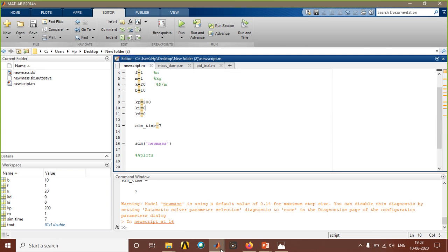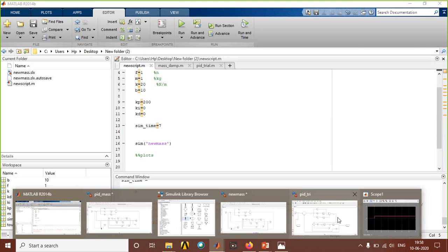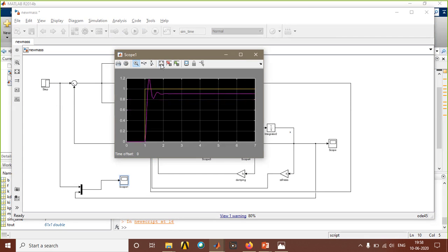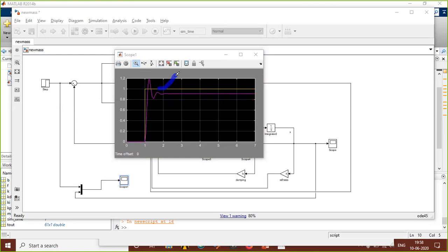But if you include only your present error, what happens is, see, it will not get settled. So this is the error which we saw at the first place without using PID controller. So this is the overshooting. This is the force. My thing will get overshot, go down. It will not get stabilized. Okay. There will be a deviation. There will be error. Okay.